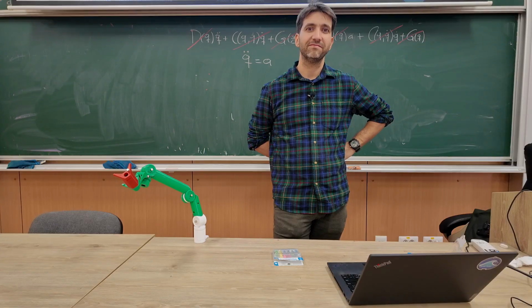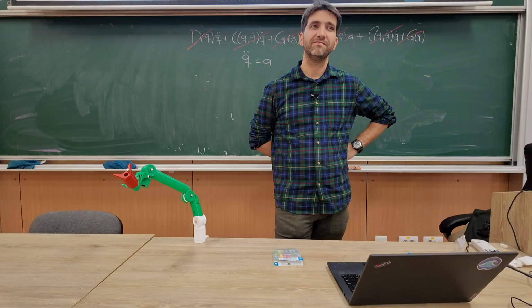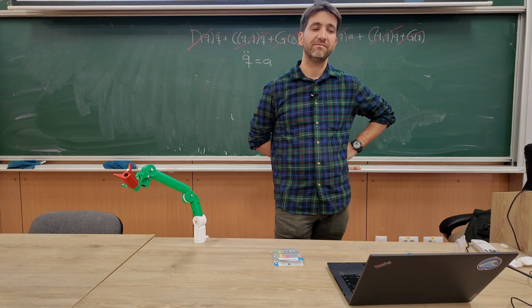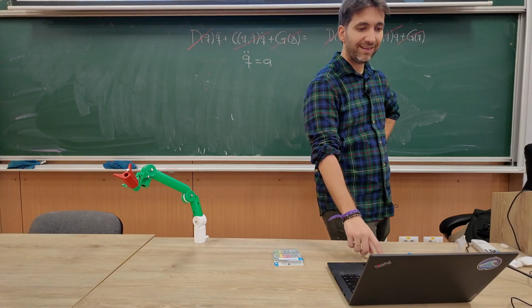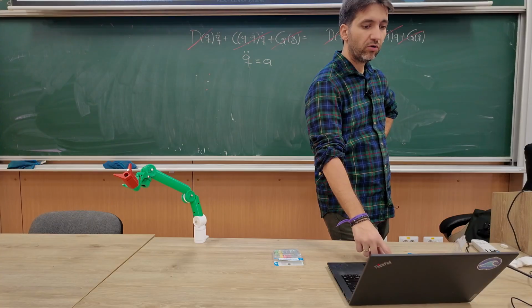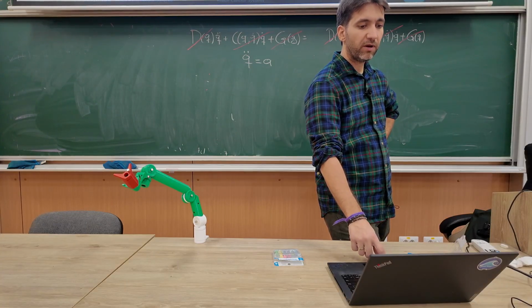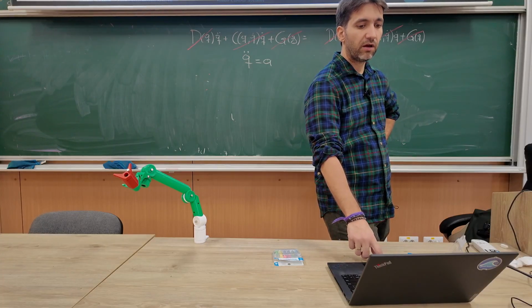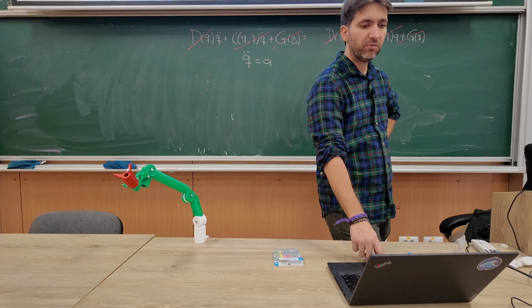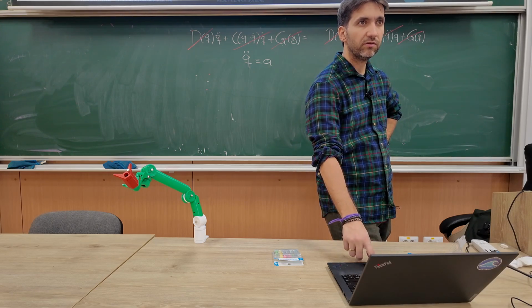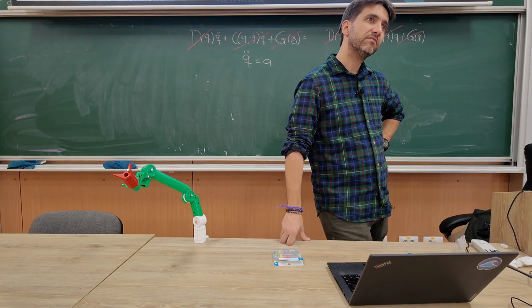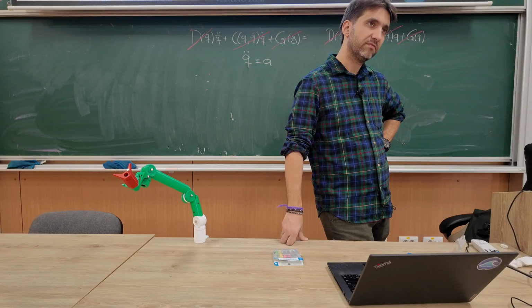Maybe we can input the joint coordinates, calculate the forward kinematics, and at the end do the same, and then subtract them. So here start with joint coordinates. Yes, forward kinematics, so I calculate the end effector, yes. And then how do I pass that in the controller? What would be the error? So I take again the end effector. Yeah. Wouldn't it be better to have the end effector coordinates, do inverse kinematics to find out the joint positions, and then put it together?